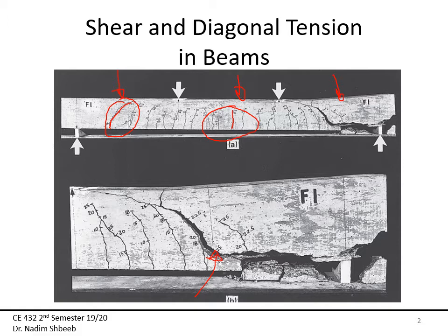So to avoid that, we like to use what we call shear reinforcement or stirrups down the road, and these will help in preventing this sudden collapse, and will also ensure that I would have a flexural failure before I will have shear failure.